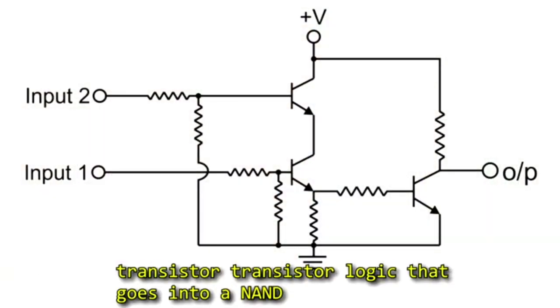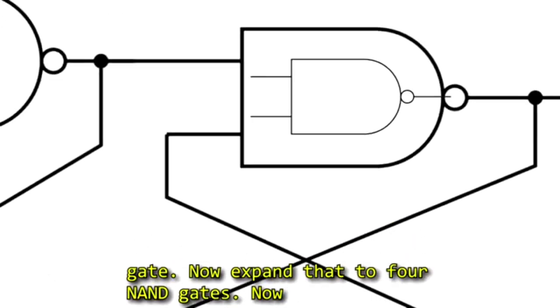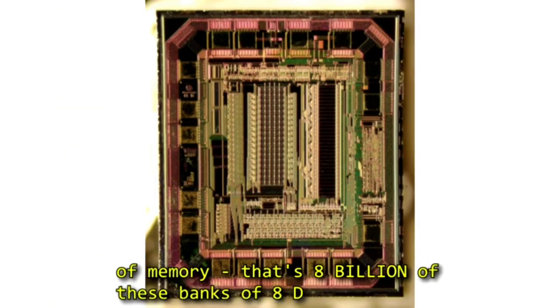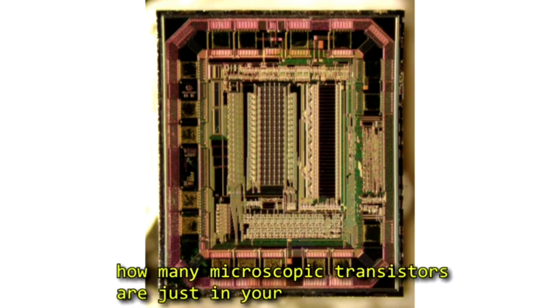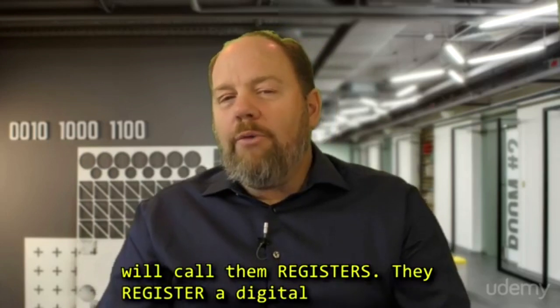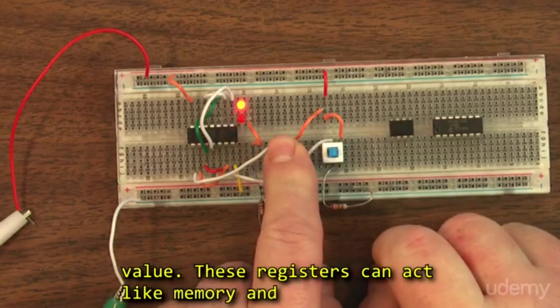Now consider this. Remember the transistor-transistor logic that goes into a NAND gate? Now expand that to 4 NAND gates. Now expand that to 8 banks of D flip-flops. Now the memory sticks on your computer might have, say, 8 gigabytes of memory. That's 8 billion of these banks of 8 D flip-flops. This starts to give you an idea of just how many microscopic transistors are in your desktop computer's memory sticks. So I will call these flip-flops, these latches, I will call them registers. They register a digital value.